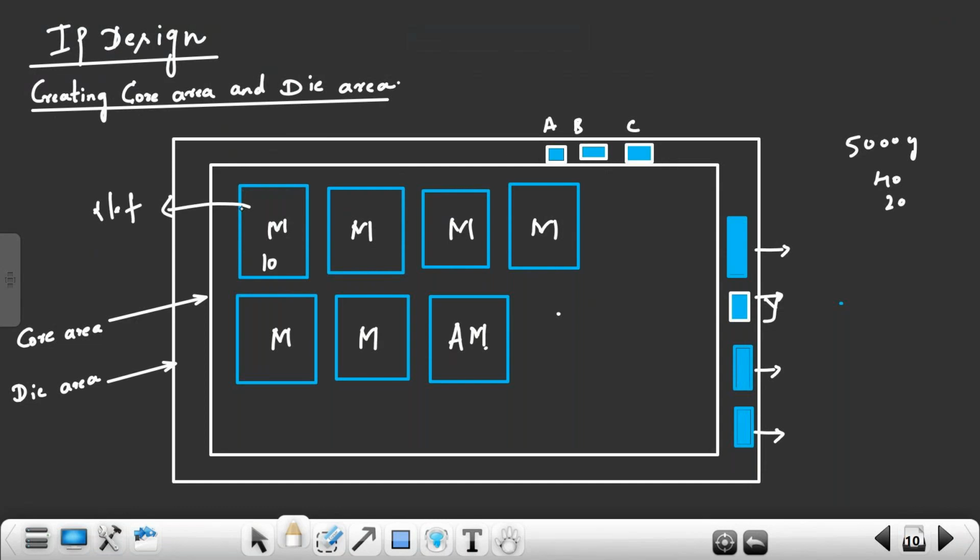See, physical design engineers are not worried about the functionality of a macro, because we want the layout. Functionality is required by the gate level simulation team, and they will be given specific functional models. But physical design engineers require only the layout of a macro, and my chip architecture has told me to use this layout. We don't have any problem. They should ensure that this macro is working fine, working good with the timing, and implementing the required functionality. Then I can directly use this LEF and place it in my design.